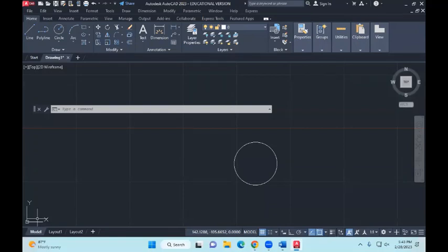Okay, what I'd like you to do now is a simple exercise. Let's make a square. I would like you to make a square using the coordinate system in AutoCAD. That square has to have a side of 100 units. Obviously each side will have 100 units, so the length of each side is 100 units. And the origin, or the start point of your coordinate, is 0, 0.